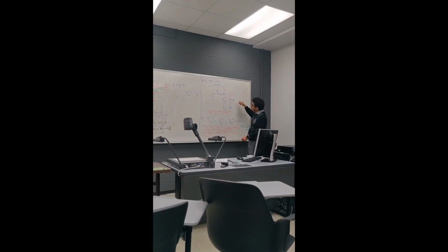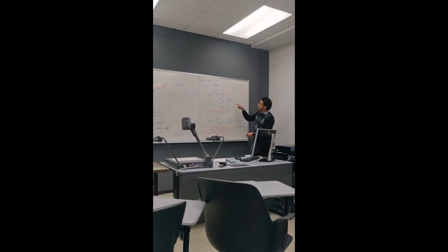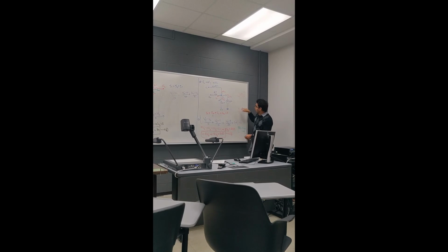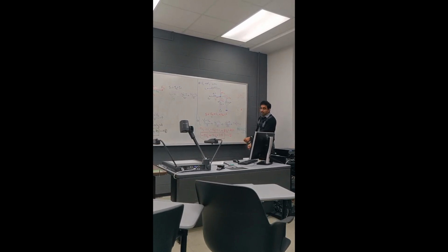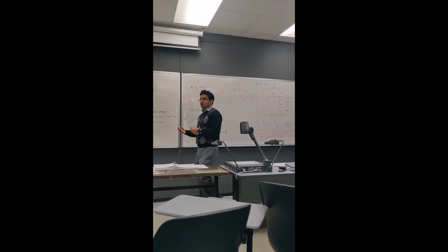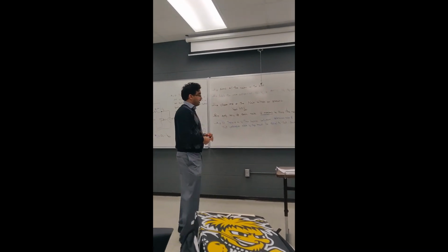We would normally write I4 as V3 minus 0 over 5, but that's wrong, because I already know there is negative 5 amperes flowing in that branch, or 5 amperes in the opposite direction, so take I4 equal to negative 5. So that's the second equation, and I end up with a nice equation. So 2 unknowns, 2 equations. Solve those two to find V2 and V3.